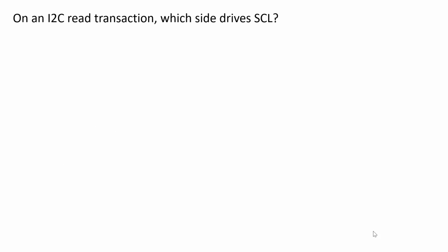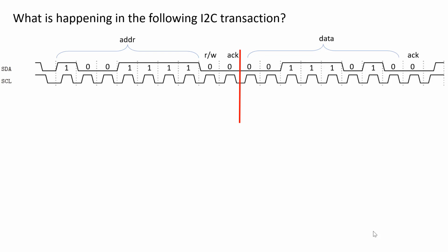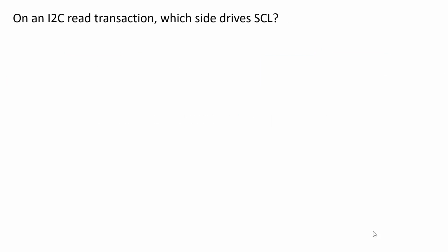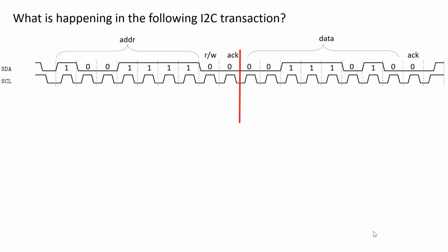And the 1 bit means not acknowledge, right? In this case, we had 0 acknowledges, right? 0-bit acknowledge, which means acknowledge, right? 1 means not acknowledge. What you might say, well, why make it active low? Well, because the idea there is that if no one's listening, remember that the natural state of this is 1, right? With the open drain. So if no one's listening, then it's going to be a 1. So it's kind of the acknowledgement. If no one's listening, the acknowledgement bit will be read as 1.